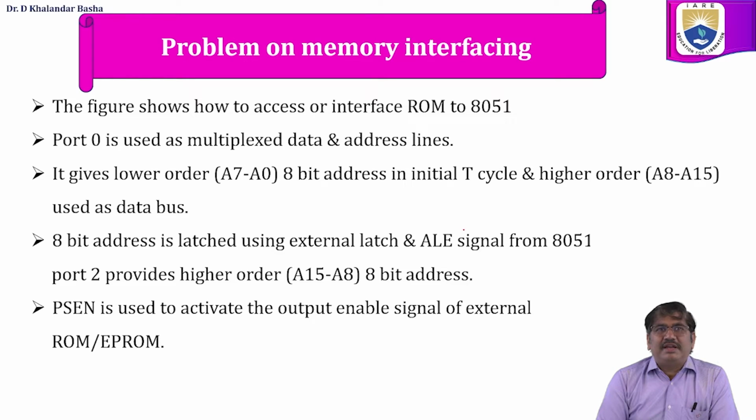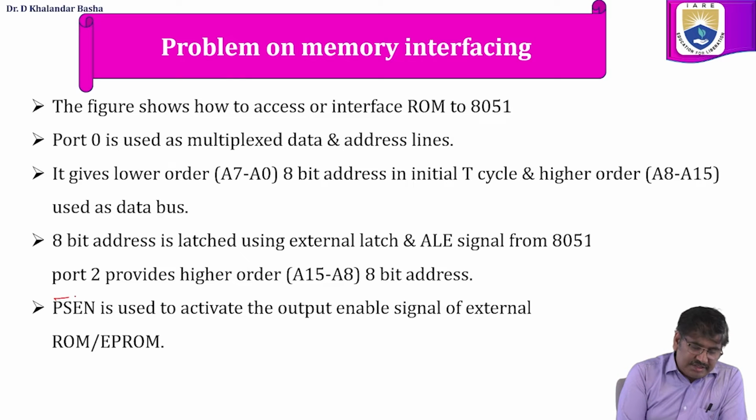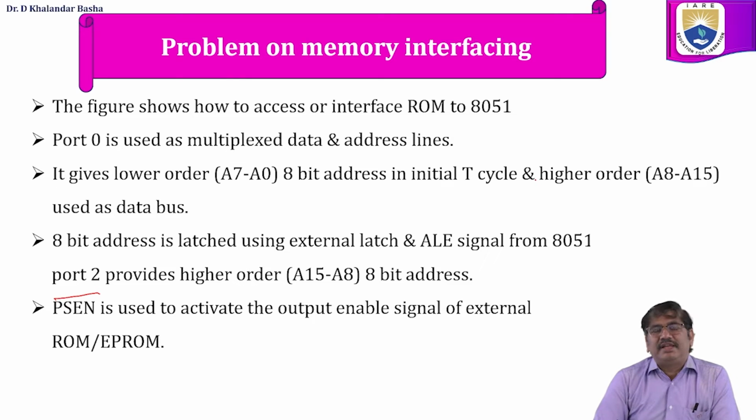The 8-bit address is latched using an external latch and the ALE, address latch enable, signal from the 8051 microcontroller. Port 2 provides the higher order 8-bit address lines, A8 to A15. The PSEN bar, the program store enable signal, is used to activate the output enable signal of the external ROM, that is our EPROM.